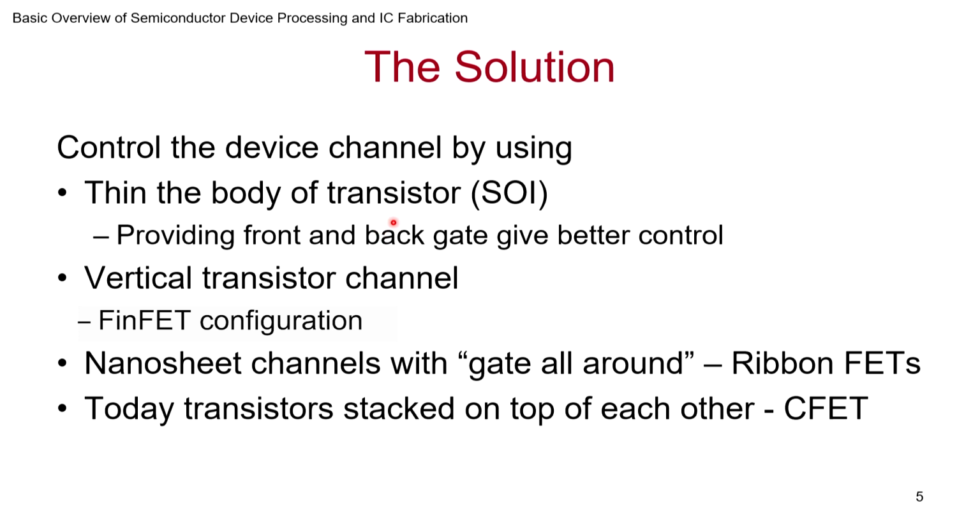What it means is this channel, I'll be showing with some diagrams shortly. The channel, instead of just controlling it from the top, you also control it from the bottom. So you have silicon with an insulator. So you have a top gate and bottom gate. So you are able to control the channel better. But even that doesn't seem to be good.